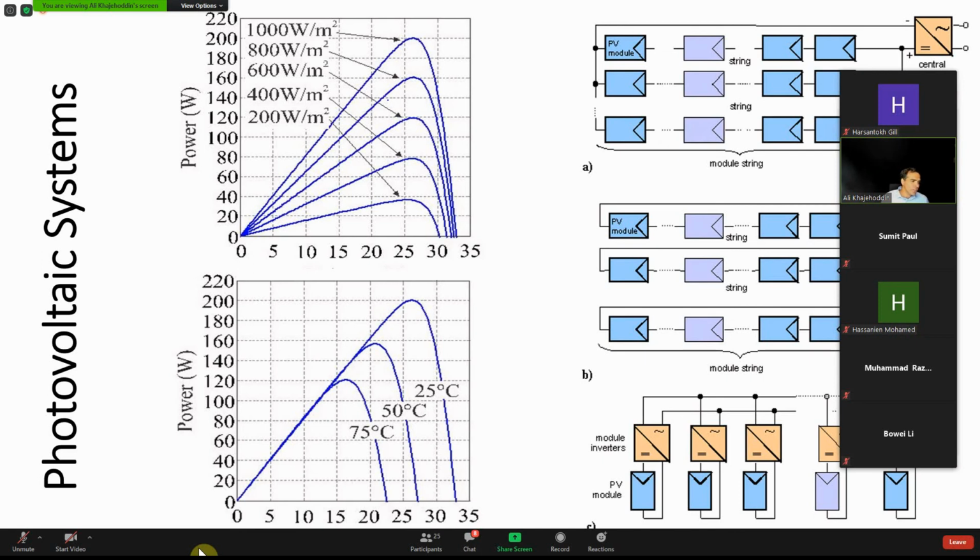And to answer your question of how many cells in one panel, we have 60 or 72, we have different numbers. It depends on the technology the panel is using. But anyways, because these are all in series, even inside those cells that we're talking about, each one of them is like a diode creating 1 volt, 2 volt for you, and each one of those is in series.